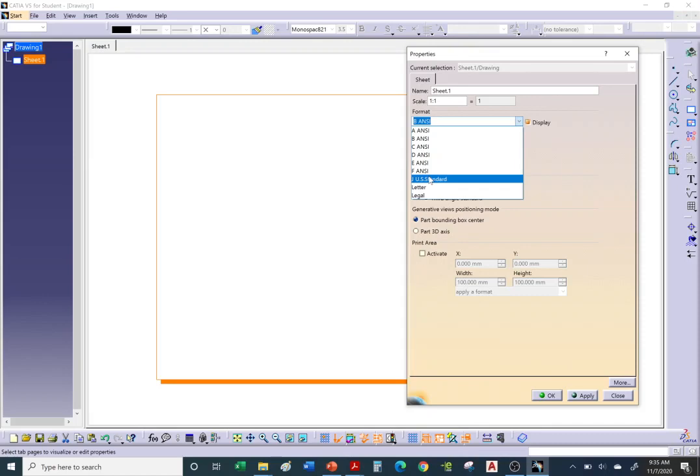There's a lot of wiring in electric vehicles, and some of the harnesses we modeled were as long as 15 feet. So we had to customize our own sheet size, 36 inches by 15 feet, just so that we could draw our wire harness flat and linear at full scale, at actual size. It's just easier to manufacture.